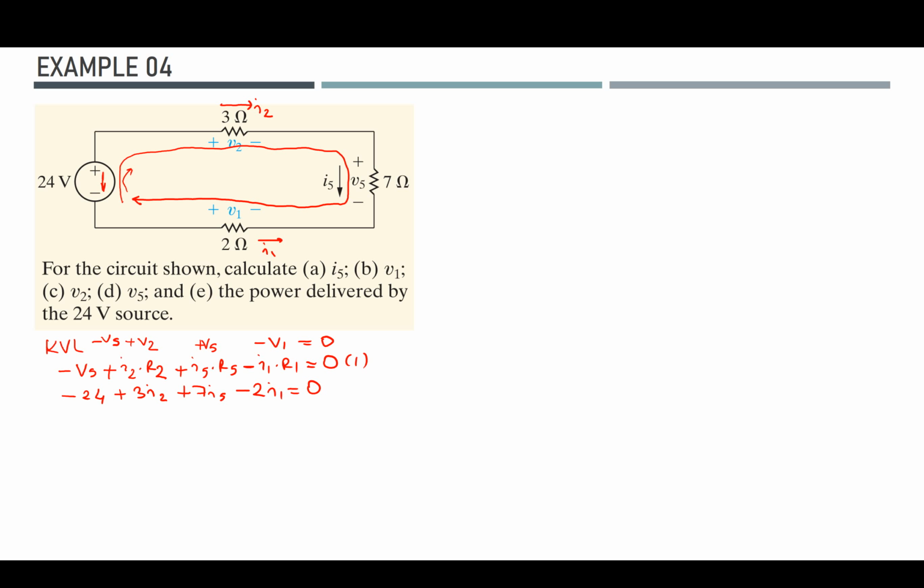In this particular case, we can also use the KCL at the circuit nodes. I have 2 nodes here, and the current flowing into this node should be equal to all the currents summed up at this particular circuit node, and there's another circuit node here. Here I have the source current, and I have the I2.